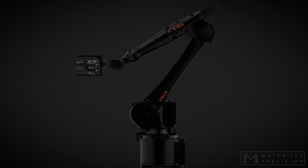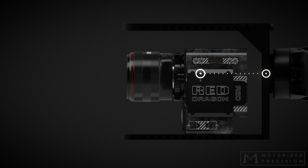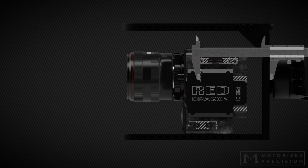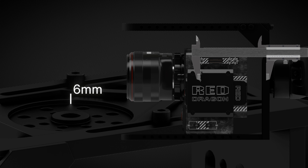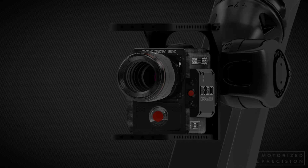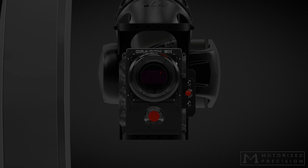If we're using a C bracket, we first need to measure the forward distance of axis 6 to the sensor. This one is easy. We can just measure from the back edge of the C bracket to the witness mark on the camera. This time, we need to subtract 6 mm for the inset mounting point. Then we need to measure the horizontal distance from axis 6 to the sensor. This will most likely be a value in 10 mm increments, like with the dovetail mount.